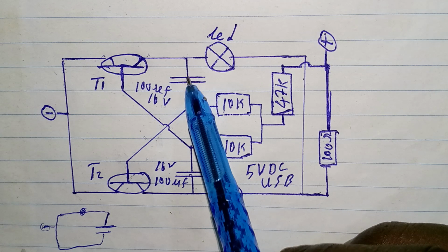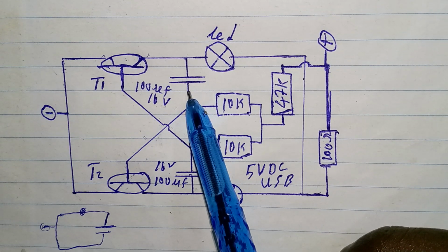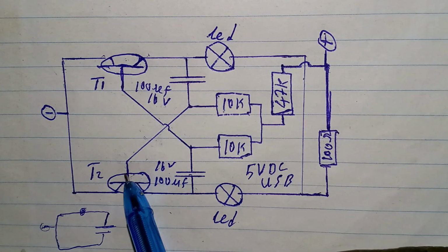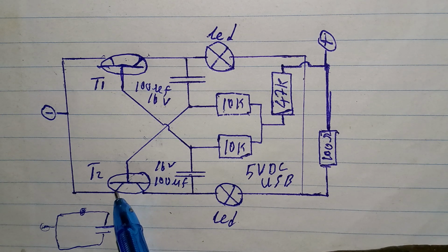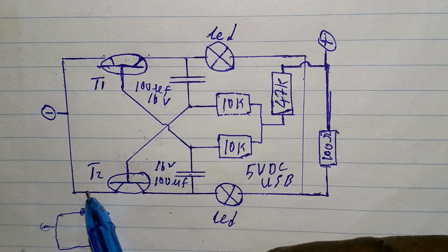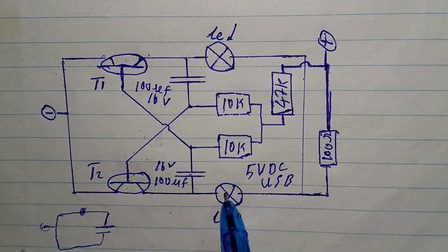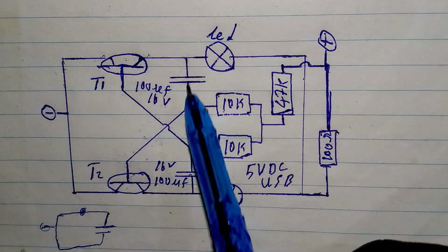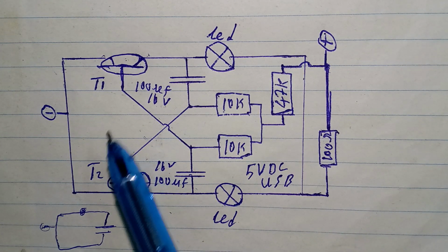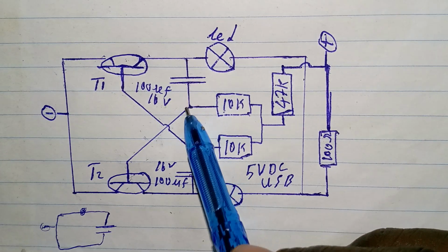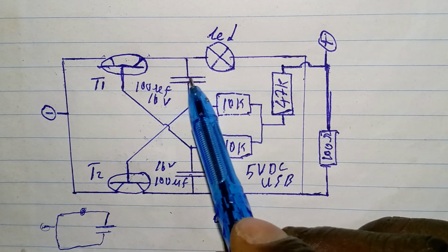Now the voltage will move through this discharged capacitor to this base, and this transistor will be switched on, thereby going to ground, allowing this lead to be switched on. And when the voltage is moving in this direction as well, this voltage that is moving here is charging this capacitor.